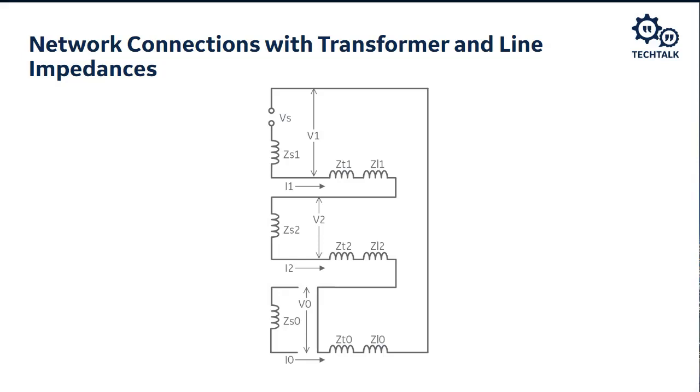If we were looking at this from the transmission system, and if our metering location were in front of the transformer, right, on the 230 kV side of that transformer, what that means is we could meter that I1, we could meter that I2, but if that CT location is just above where the I0 is there on the primary of the transformer, there's no I0 flowing through that open section there. So we would not see zero sequence quantities on the primary of that transformer.